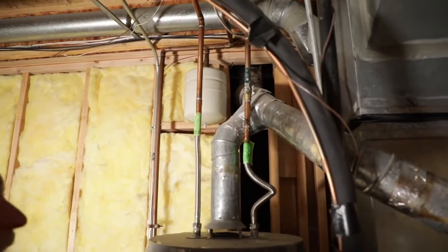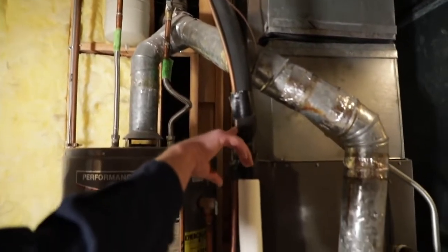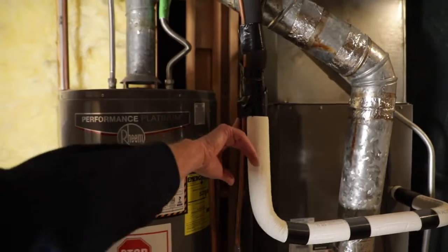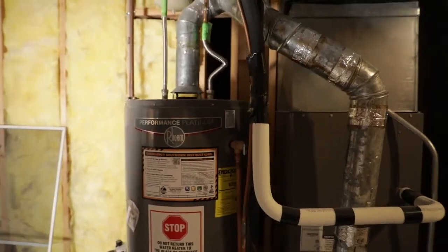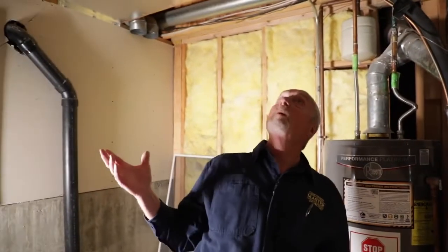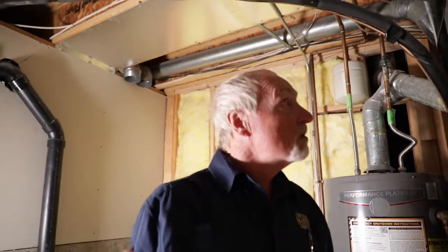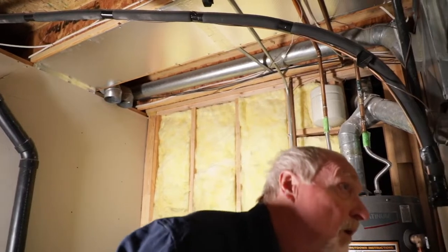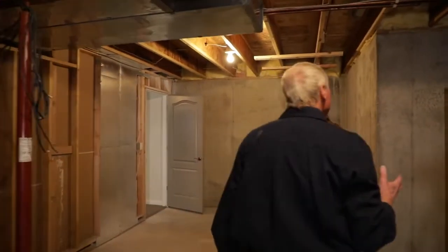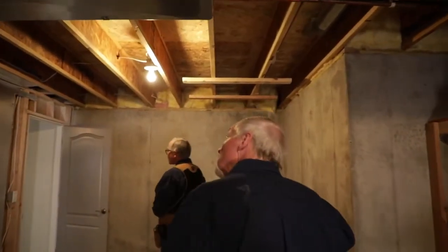We earlier had comments with Ray about the refrigerant line not touching the gas line here, which is something we would like to keep separated. And so what we're looking at here, frankly, looks pretty good. We will continue walking around here, looking at our copper, looking for evidence of leakage, checking our gas line.